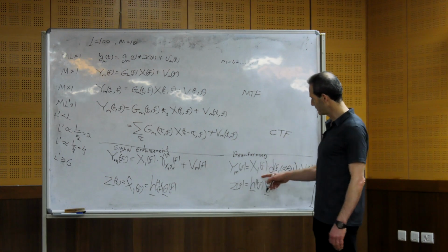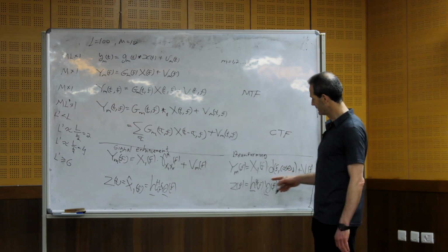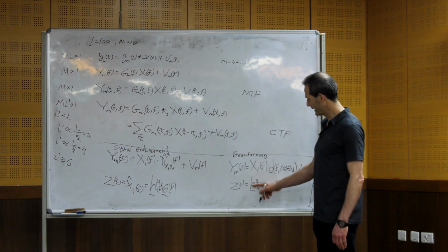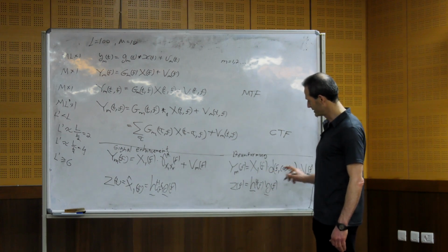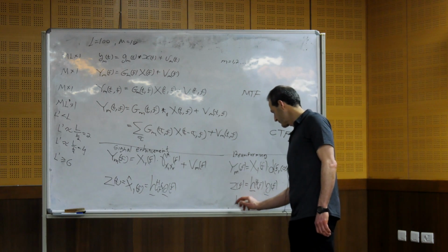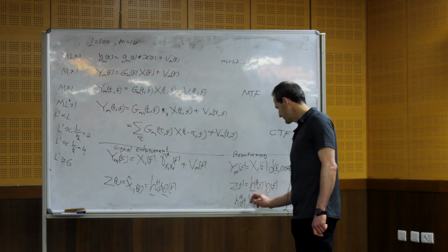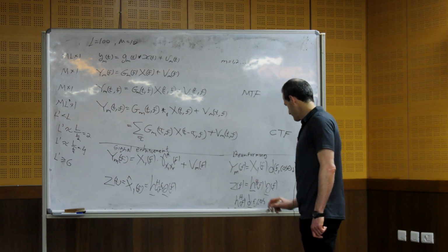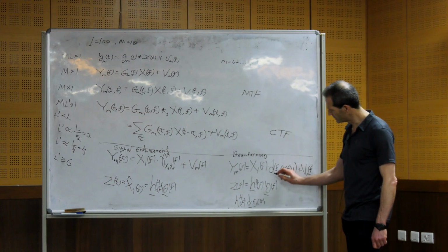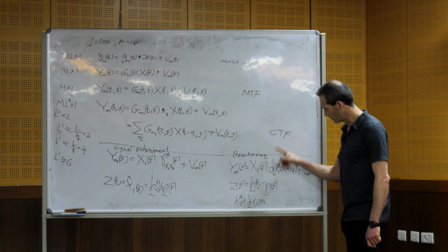So here we need to apply a requirement that if the beamformer h is applied to the steering vector d_f, by the way, here you need to add m, this is the m element of the steering vector.